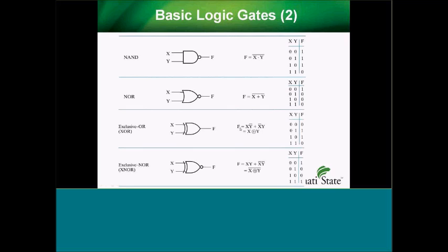The XOR basically is like the OR, except only one of them can be 1, and the XNOR is just the opposite. I also like to specify that the XNOR is commonly used to indicate where you have two signals that have the same value. So if they're both 0, it's a 1, or if they're both 1, it's a 1. So this is used in comparator circuits. I try to tell them bits and pieces here and there about what each one's used for.